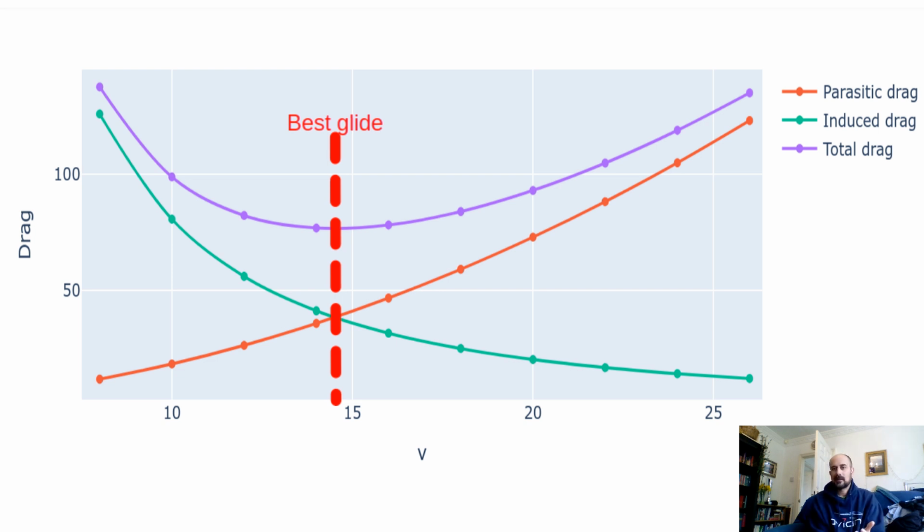Also, bear in mind that this case is for a glider in steady, straight and level flight. If you're banking, then you're going to be pulling G-force, which means the wing is having to generate more lift. Say you're really tightly cranked up in a thermal and you're banked at 60 degrees, that means you need to generate twice the normal amount of lift. It's a 2G turn.